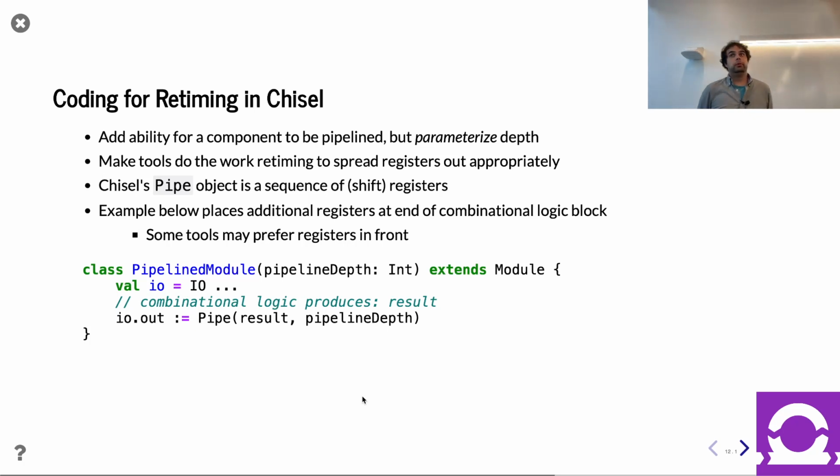You run a tool flow of all 3 modules together. So the question was, if multiple modules are feeding into each other, how do you make sure you're working on the one critical path? My answer is you do all the modules together. You run your entire design, because a lot of times the optimizations and placement and that kind of stuff is a global problem. If you do things in isolation, you can get numbers, but those tend to be the best numbers that are possible. Once your module is not just in isolation, where it can use all the space it wants, but is compacted on multiple sides by other designs and competing for routing resources, that's going to be a more realistic number. So you do want to run the whole design. Unfortunately, running the whole design takes a long time because it's a big design and slow tools.